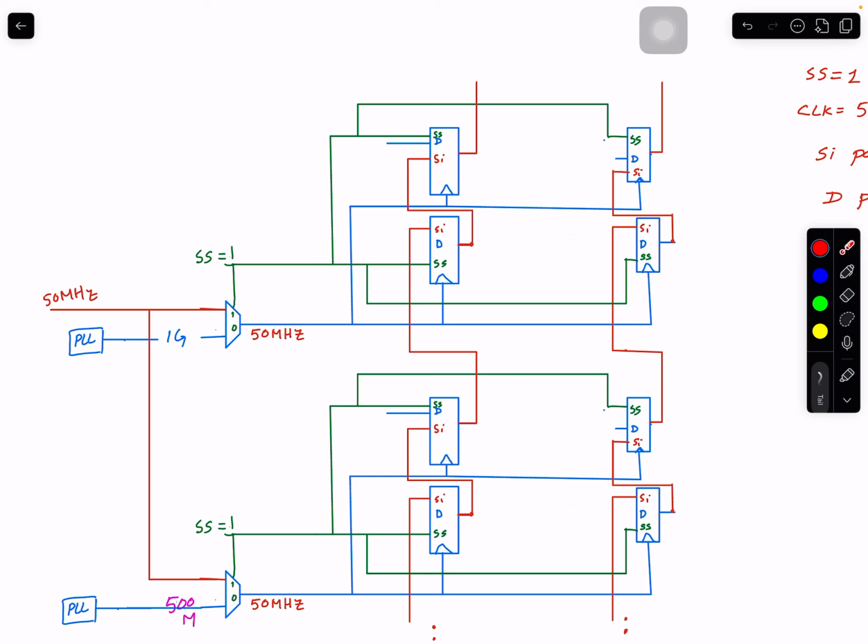Okay, makes sense? So you can create as many modes as you want, but the disadvantage is it will be another timing run. Another run where you will read a netlist, you will read the libs, you will read the SPEF, you will read the constraints. Okay, you will make sure check timing is clean, you will make sure all the logs are good, you will make sure all the reports are good.